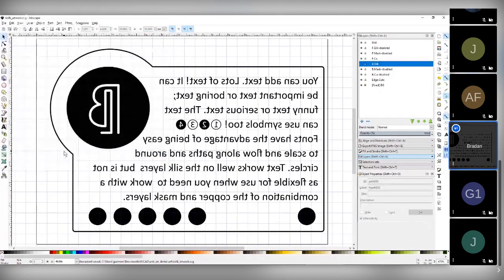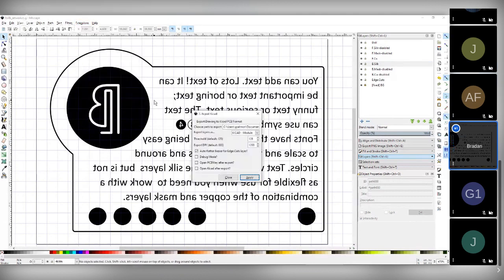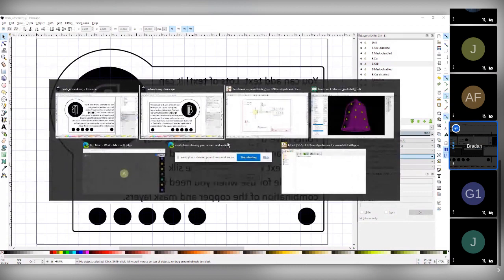Okay. So the next thing we do is we go in here to extension, we run the extension, and we just do an export. And the only thing that's a little confusing here is this remembers whatever the last path is you worked with. So you have to keep changing this, or put all your footprints in one place, which we learned isn't the best way to do it on a project by project basis.